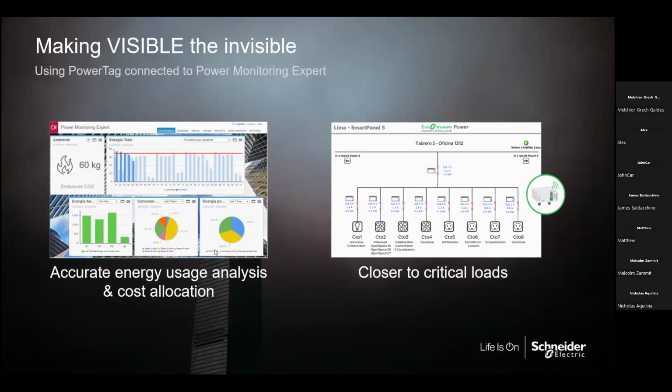So you have to get some readings from your loads, and not only, like I told you, the incoming, you have to allocate each and every one of these consumptions. So here is the output, or like I told you, you can open the web page of the panel server itself. You could also see the output.